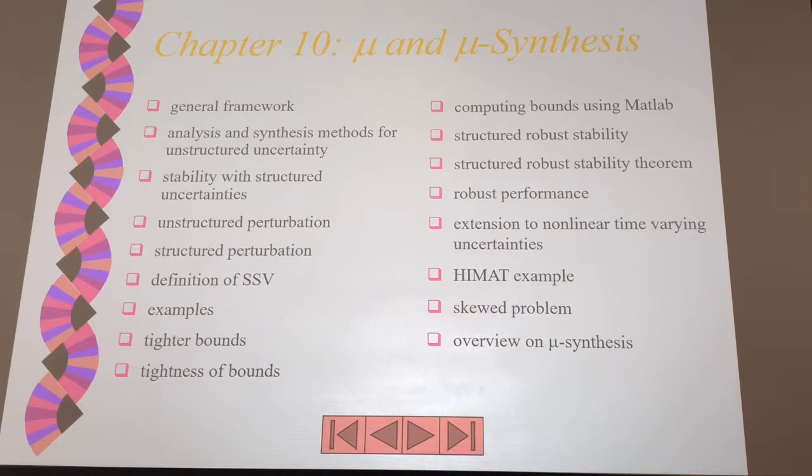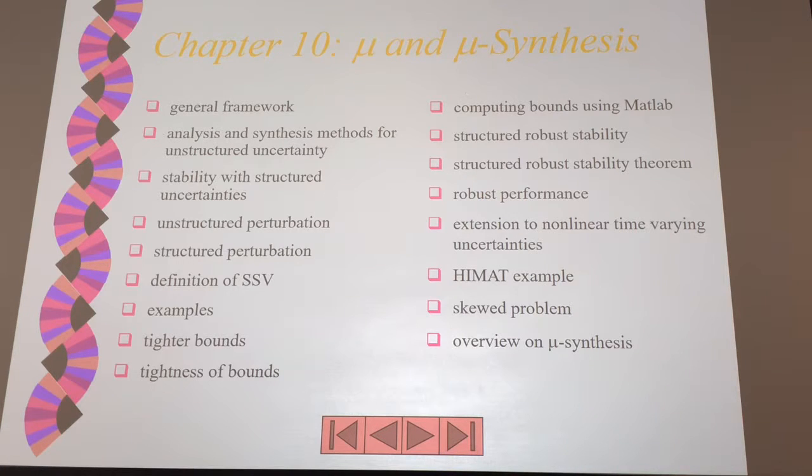I hope you know that what we are learning is very useful. Okay, very useful. I agree, very useful. But it may not work in certain cases. Okay? So that's why we need something further. Say, for example, we return back to control parameterization. It's also known as the Youla parameterization. Basically, I have a family of robust controllers that can do the job, okay? They stabilize the system, but which one is the best? So you basically make the robust controller parameterized, then you search for the best controller.